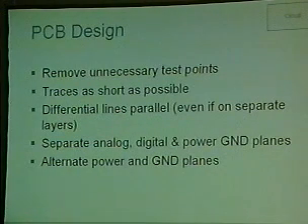So you want to keep your traces as short as possible for that same reason as far as noise, but it also might make it difficult for an attacker to access those lines. You can also route the signal traces on internal layers of a multi-plane board, which is good for production but not good for development, because then the engineers won't be able to access those lines. Also with vias, you can have buried vias, which would also be in the inner planes of the board, which again is good for the production but not good for development.